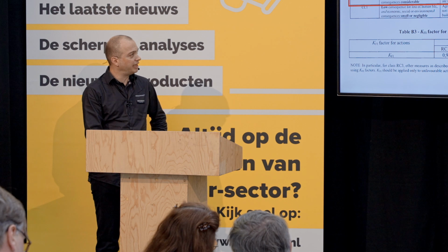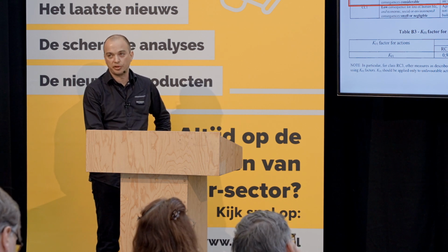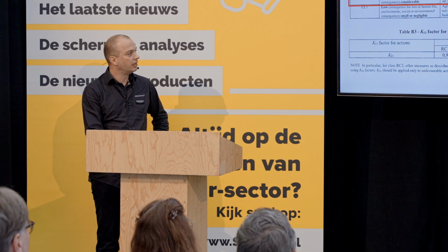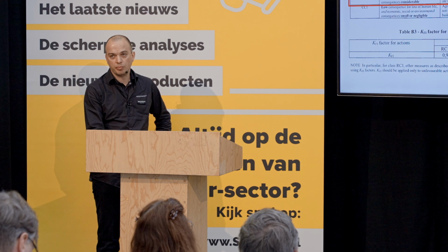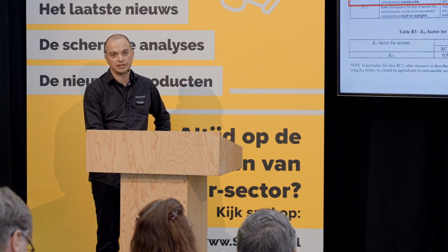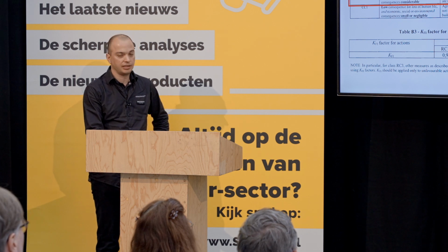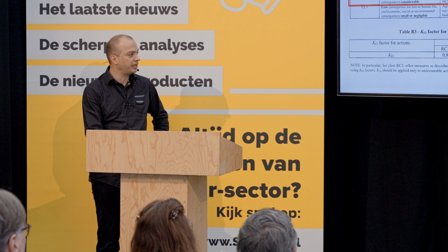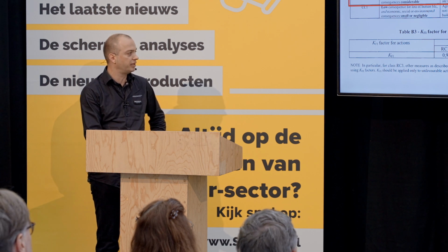Now let's talk a little bit about the consequences class. The default value for the consequences class is CC2. In rare cases, you may have CC1 or CC3, but according to the Eurocode, it is CC2. And that consequences class is associated with a force importance factor, KFI, of 1.0.